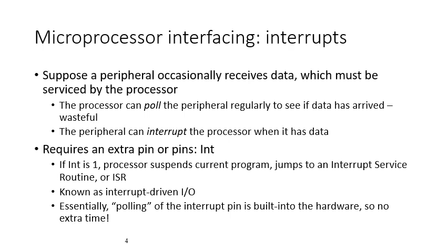Now this requires an extra pin or pins. Normally for interrupt we have the INT pin. If INT is 1, the processor suspends the current program.